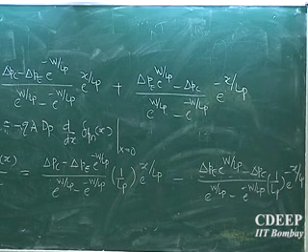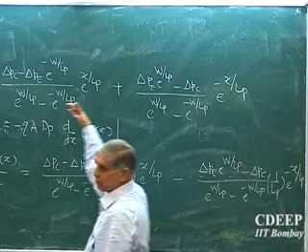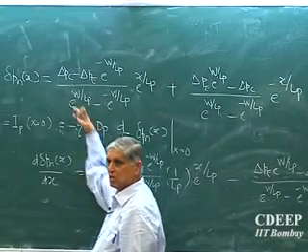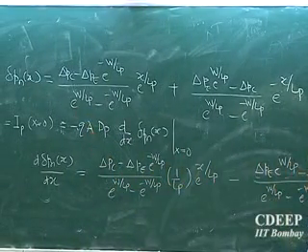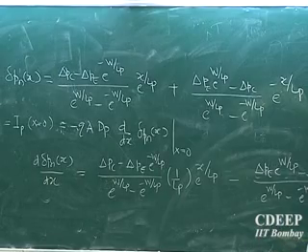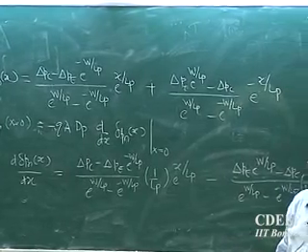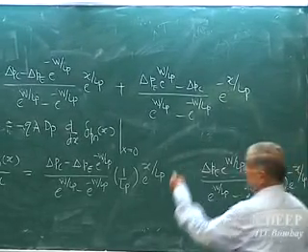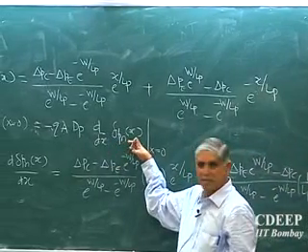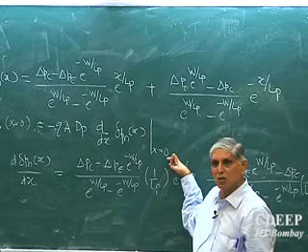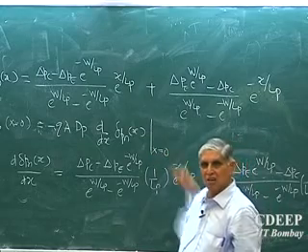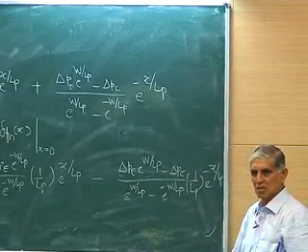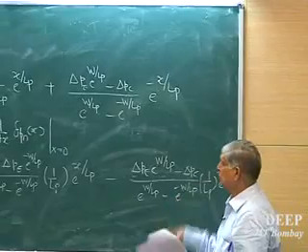Is that clear? Please remember, these are only voltage dependent terms and technology or device dependent terms. There is no x part in this, so they remain constants. So now I substitute the two cases of interest, at x equal to 0 and at x equal to w. The second current I will get is the same, but at x equal to w, and once I get this, I will be able to find both collector current as well as emitter current. Is that correct?